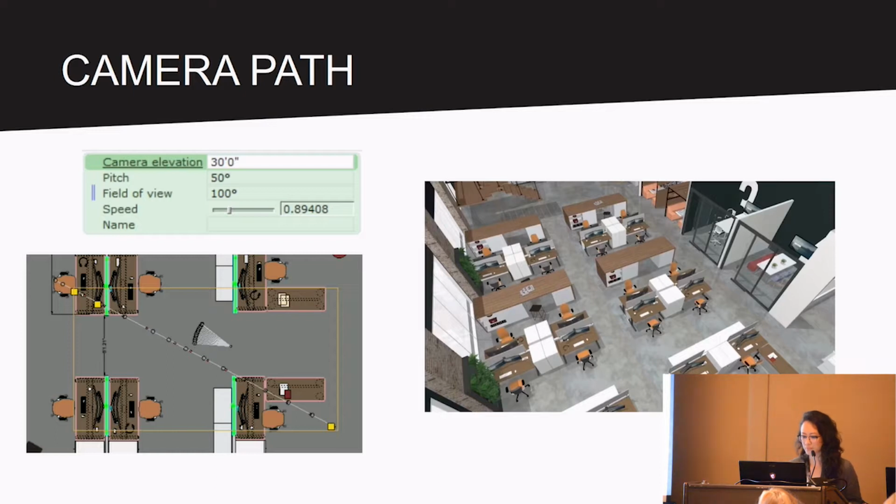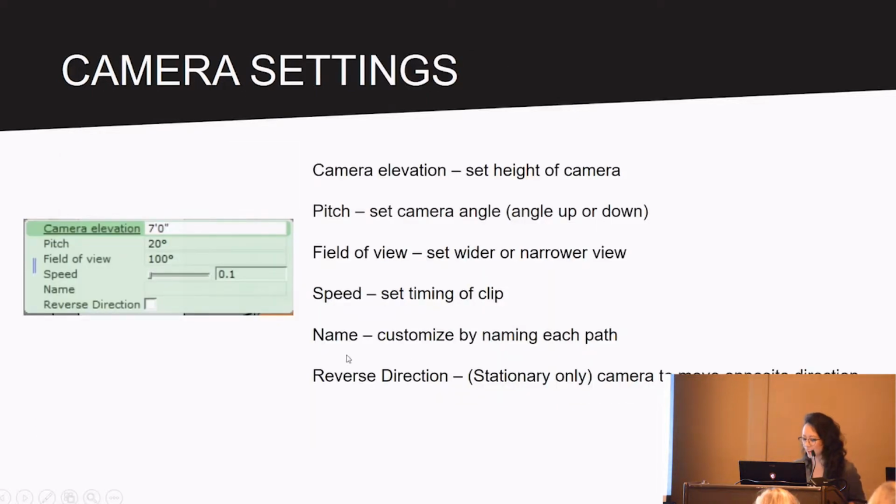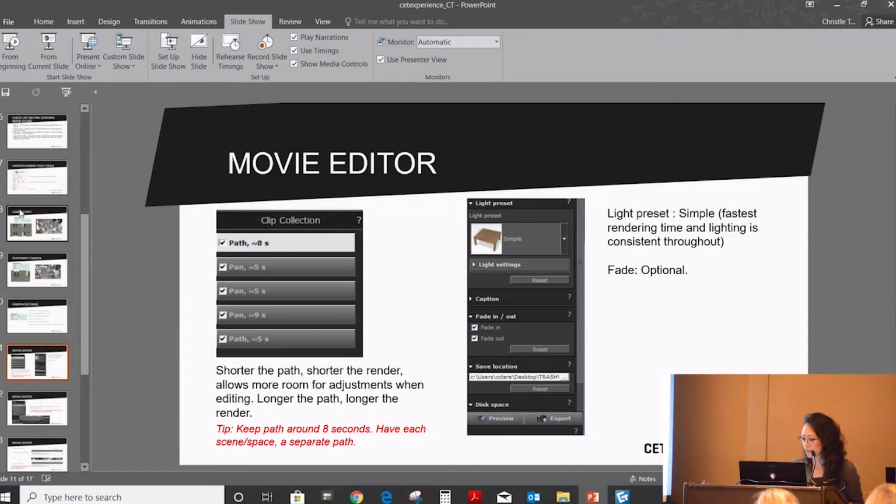So this is a camera path that I would usually use, and it's like a drone. You're welcome to write down the exact settings that I used. The only time I would tweak it a little bit is for every space or project, because it's different. But for the most part, it is around that setting. Notice that it's just one straight line, because I like to keep it simple, and really it does the trick.